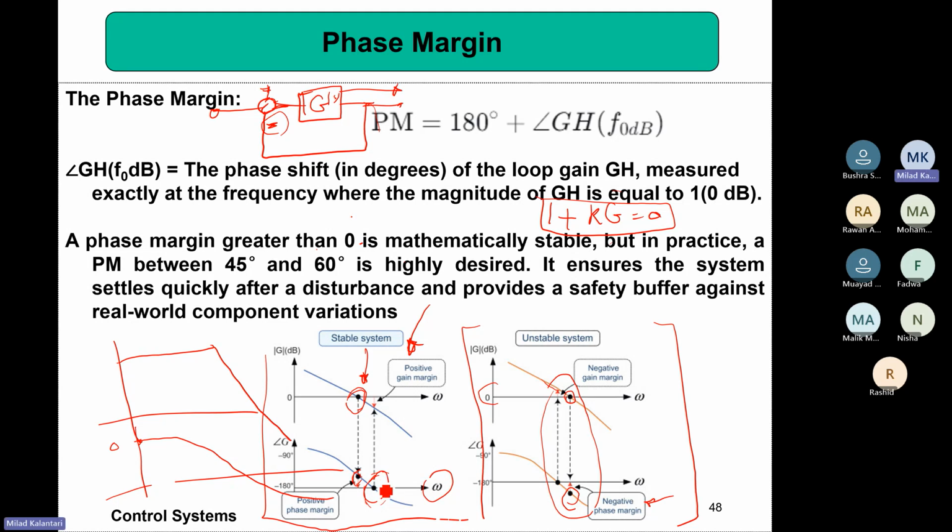The reason is once the phase is reaching 180 degrees, the amplitude is too low, lower than 1, right? No, the amplitude is always a positive number. In logarithmic scale, yes, negative. But in the logarithmic scale, below 0 means the amplitude is less than 1.